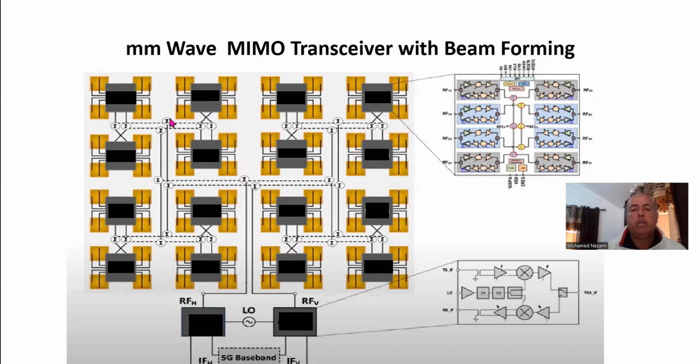And the passive components in here, you need all these passive components. For the divider network, like I showed last time, you could design it either with Wilkinsons using stripline technology with thin film embedded resistors, or you could use off the shelf thin film two-way, 4-way splitters. And that's what I did, okay?